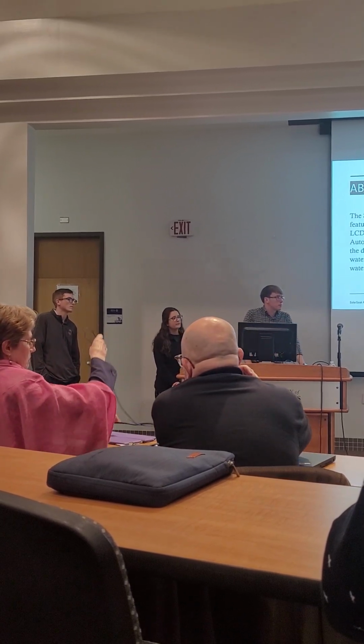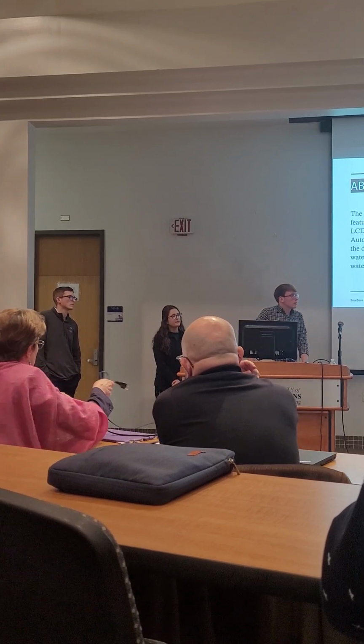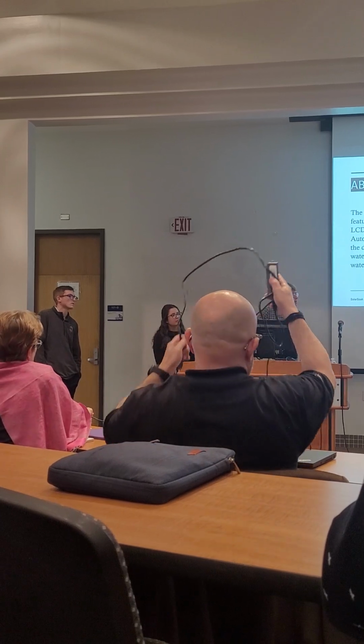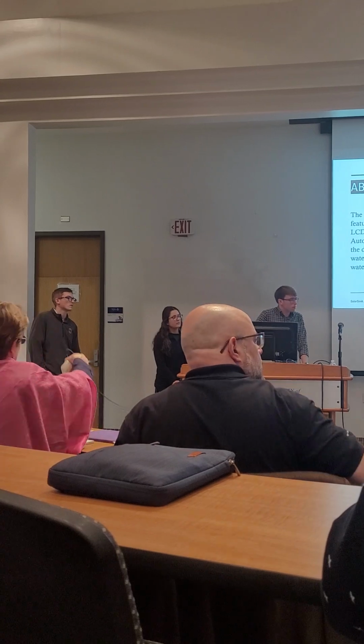Yeah. Okay, this is my feedback. If you would like to start a relay with the micro, there's a problem. Just use a buffer between the micro and the relay.